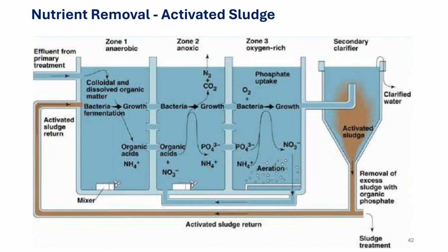And the phosphorus is settled out as sludge eventually. Now here's an activated sludge plant that was designed to have all three of those environments. We have an anaerobic zone, an anoxic zone, and then our aeration zone here. So in the anaerobic zone, we're preparing our phosphorus accumulating organisms. The anoxic zone is denitrification, and in the aerobic zone, an oxygen-rich atmosphere, the BOD is being removed and ammonia is being oxidized. And notice at the bottom here, we have our nitrate recycling flow.